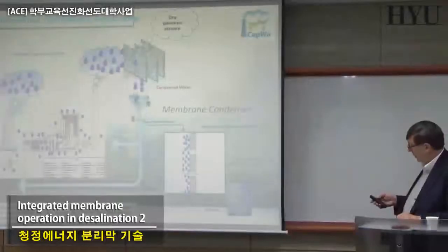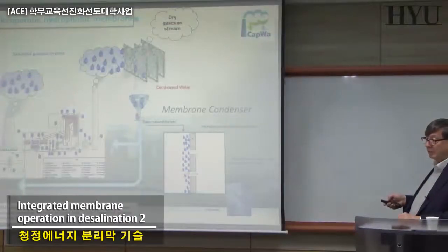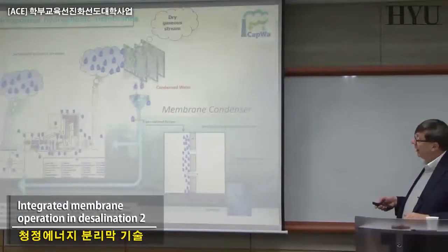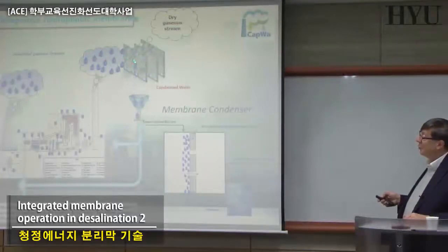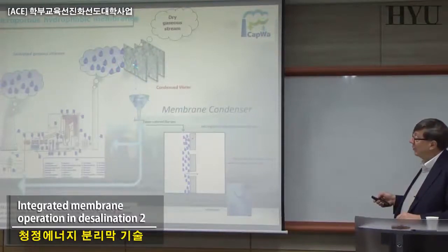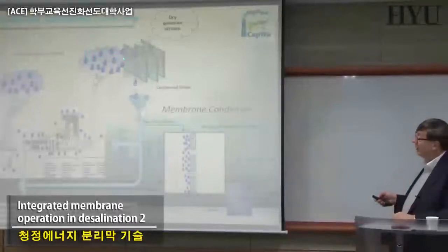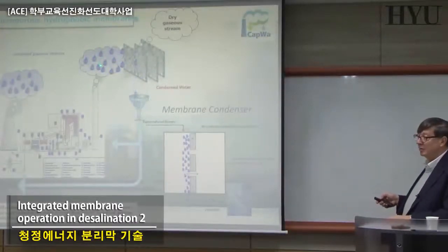Let me see, in this way. You have just your flue gases, and that can be from any kind of company, power station or textile, etc., and you just send them onto your membranes. Now, if you just cool down the membrane here, this is coming out at 90, and here, if you make the modeling, you can find now in the literature, we are working at 80, 82. So 10 degrees, 18 degrees, you can recover 20%, 50%, 90% of the water which is present here.